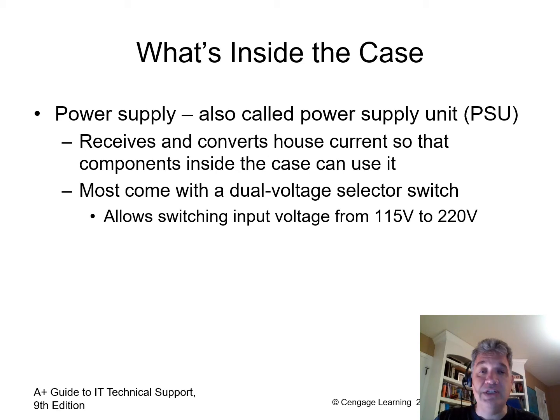Power supplies should be replaced in their entirety, and your used power supply should be recycled. So please consult your local solid waste department to see where you can dispose of computer and e-waste safely. A disposed of or old power supply can hold a charge for a considerable time, and you do need to make sure that you take proper care in disposing of it.